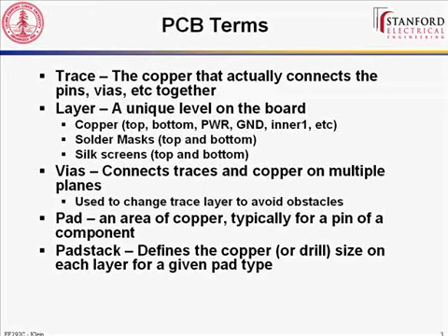Does that make sense? If you had a through-hole component, like your LCD screen or your keypad, that actually has drilled holes all the way through, there's information on every layer in the pad stack for that component. Because you have a drill hole, and then on your inside layers, even though you may not be using the inside layers, you still have to specify the maximum copper around it. If you don't have plated holes, it generally costs a lot more from your PCB fab company. So you're generally going to have to break these out into each layer.